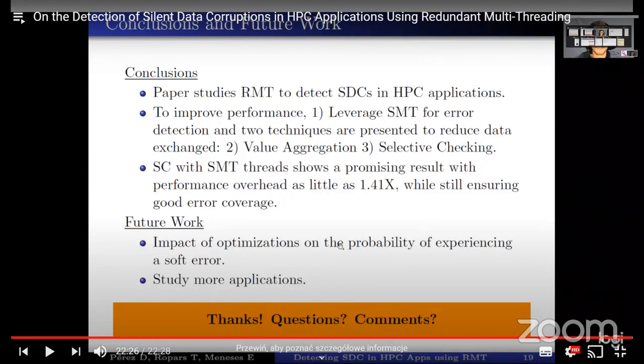Okay. And with the data values that you're injecting into, I assume these are floating point, did you pay attention to where in that bit stream, whether there were high-order portions, or was it just random selection? Yeah, that is also something you can configure in FlipIt. You can say in which bit of the selected register the error is going to be injected.